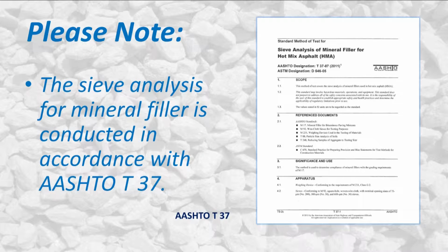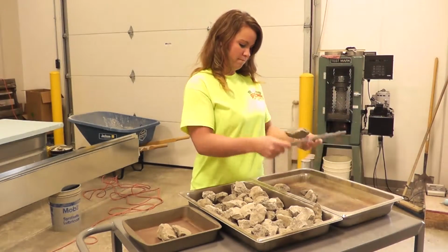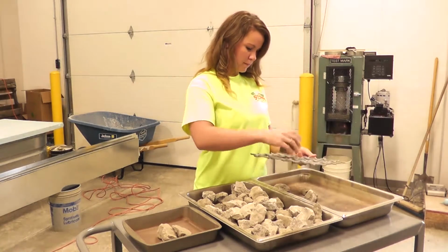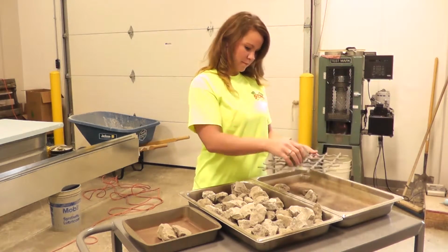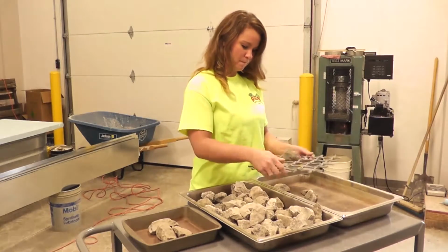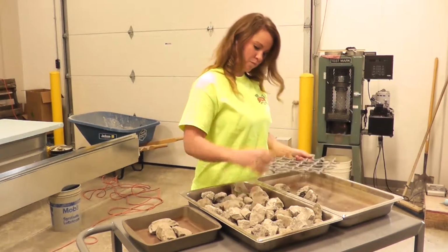The sieve analysis for mineral filler is conducted in accordance with AASHTO T27. Particles larger than 3 inches should be hand-sieved. When passing large stones through sieves, do not force the aggregate through the sieve openings.